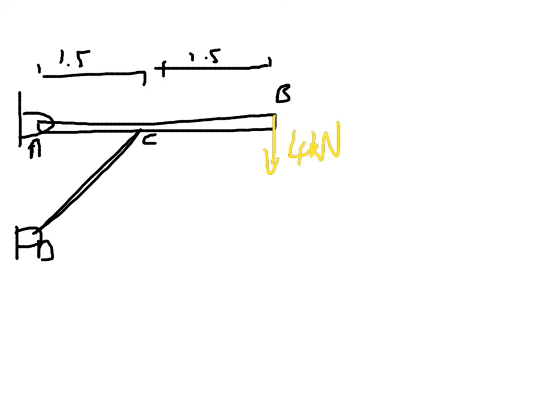Now it's coming at that angle because you'll notice that CD in the diagram is a two force member. So we may not know what's happening specifically at D. We may not know the magnitude of the forces in the X and the Y direction. We may not know the size of these forces. But we know that the resultant force at C and at D is going to be equal in magnitude and opposite in direction.